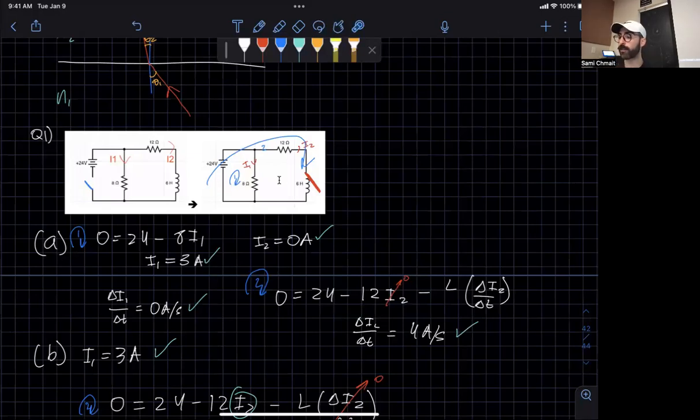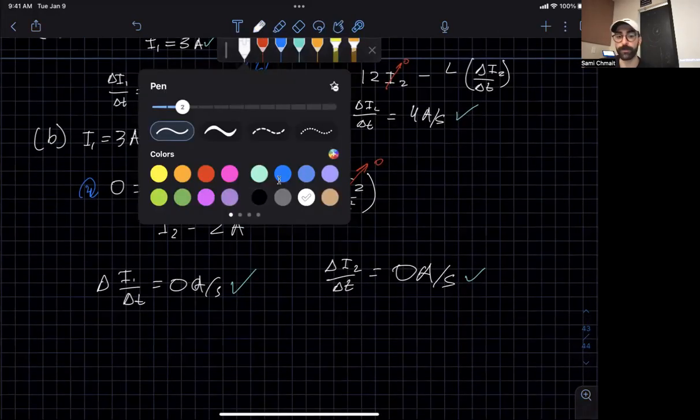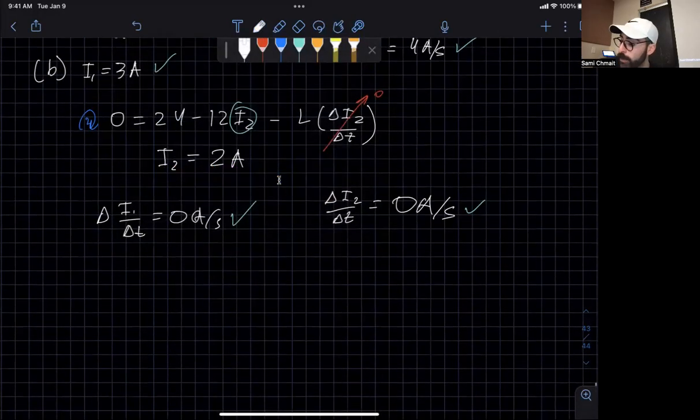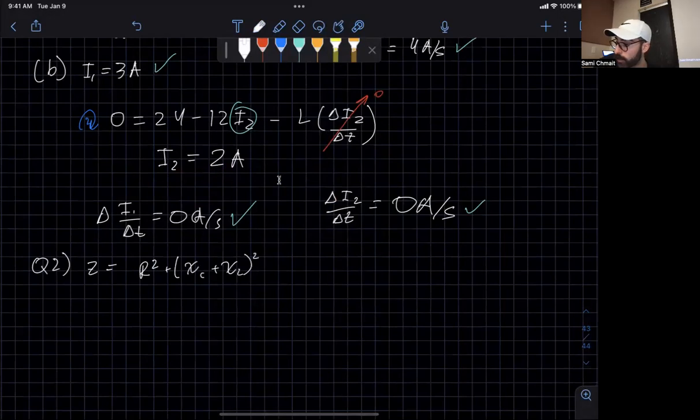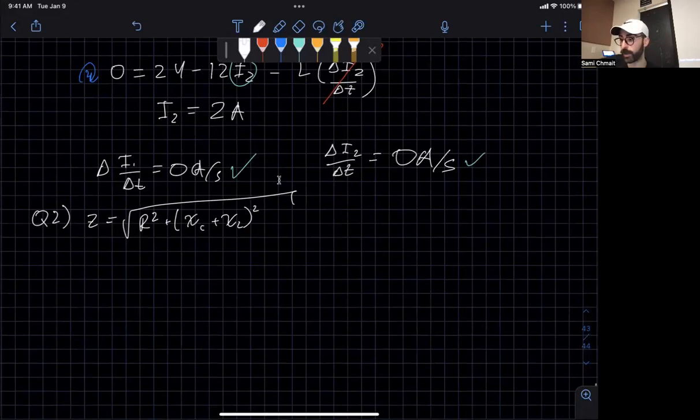Now to calculate this, the first thing you'll need to do is find the impedance value. And how do you find that impedance value, which itself is basically the resistance of everything in that system, right? We have an inductor, a resistor, a capacitor. What is the resistance contributed by each of them? That's what the impedance tells us. That Z is equal to the square root of R squared plus (XL minus XC) squared, like this. Well, we know what resistance is, but we don't know XL or XC. So we need to first find those.